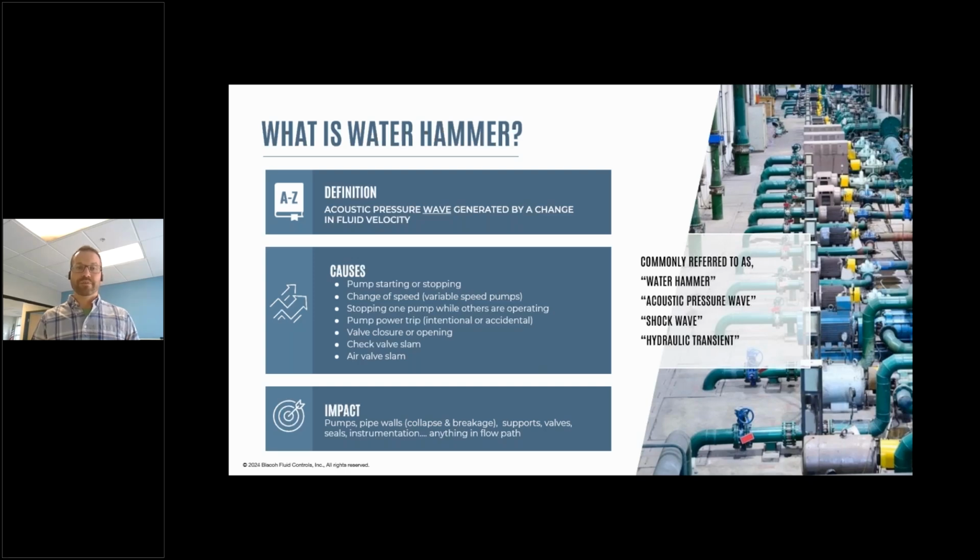And these can also happen when you have a valve that closes quickly or opens quickly. A good example of that is a check valve, right? A check valve is in most cases going to slam closed. Well, that's an instantaneous change in fluid velocity. And there are also other things, like air valve slam, that can cause the same kind of thing.